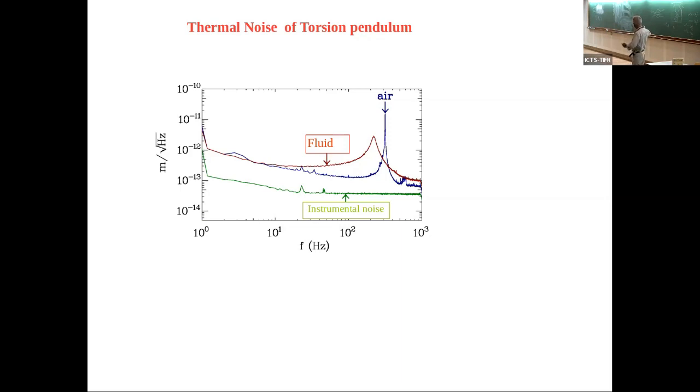But now if you take the same cantilever, you dismount it, and you put, for example, a thin layer of gold. You know that gold is very plastic. So you are increasing the dissipation a lot, but in a very strange way, in the sense that the Young modulus is actually dissipating and is not anymore just a real quantity. So you can simulate this with an imaginary part. And you see that this part is due, in my case, to the plasticity of my metals. Again, if I put a layer of gold on a cantilever, that is what I get.